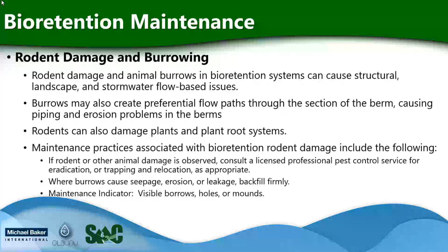The maintenance practices include, if rodent or other damage is observed, consult a licensed professional pest control service for eradication, trapping, and relocation as appropriate. Where burrows cause seepage or erosion or leakage, backfill firmly. And your maintenance indicator is visible burrows, holes, or mounds.